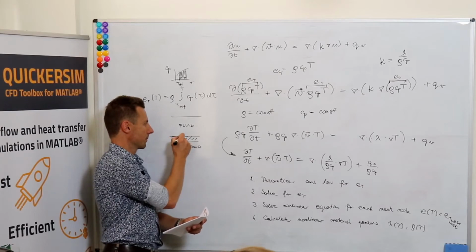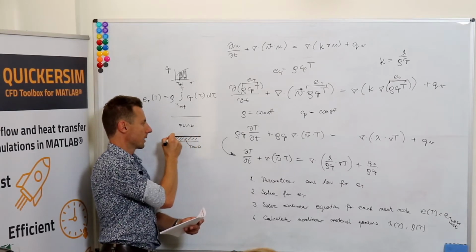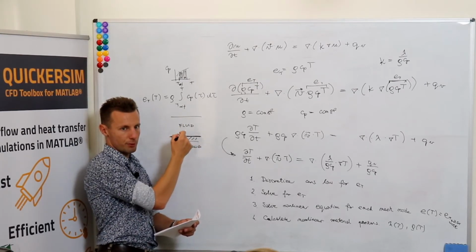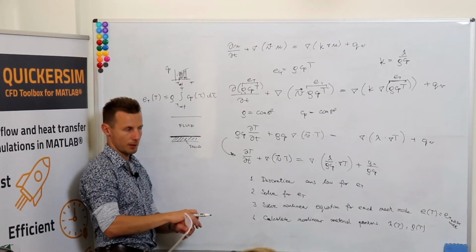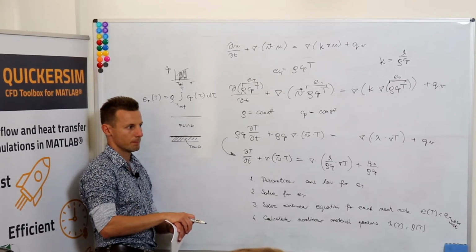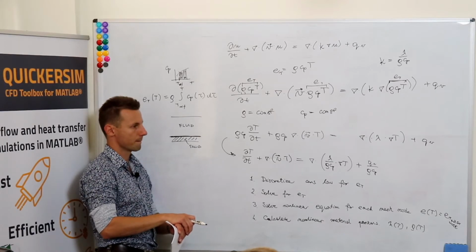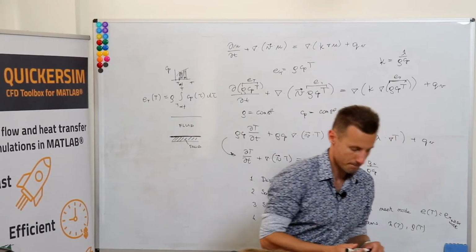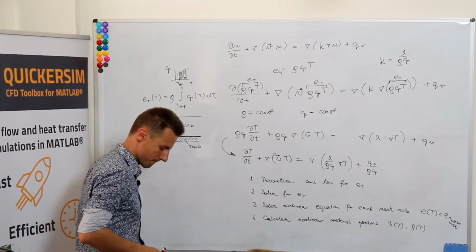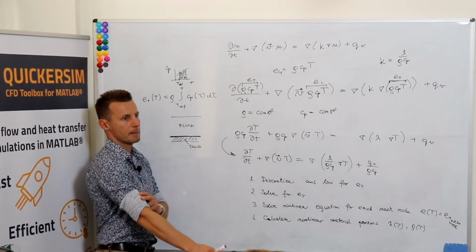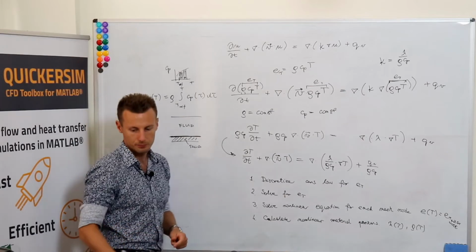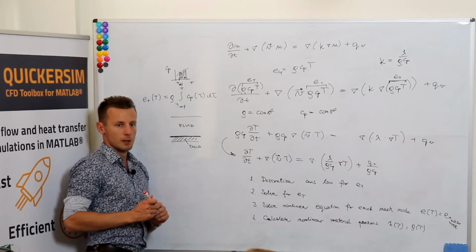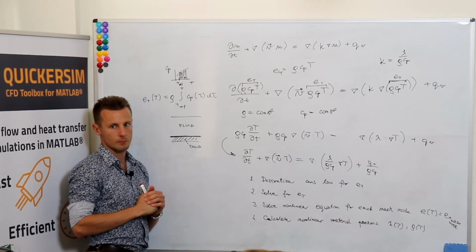So here. Let me check if you understand me correctly. We are solving the coupled problem with the fluid and the solid in our domain. You have to apply boundary condition, for example, on the bottom of the solid and on the inlet of the fluid. Because if you are solving coupled problem, then you've got like diffusion matrix in the solid and then convection diffusion in the fluid. Exactly. Because you are trying to evaluate convective heat transfer coefficients directly from the matrix, not assumed.